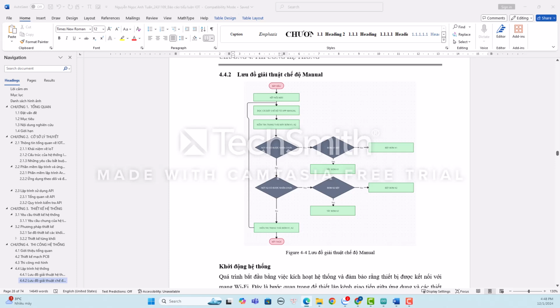The system starts up and downloads the mode setting from the app. Check the status of pumps K1 and K2. If the K1 pump control is processed, the K1 pump control push button tests the system. If K1 is fresh, the system checks the current status of the K1 pump. If pump K1 is on, the system turns off pump K1, and if pump K1 is off, the system turns on pump K1.